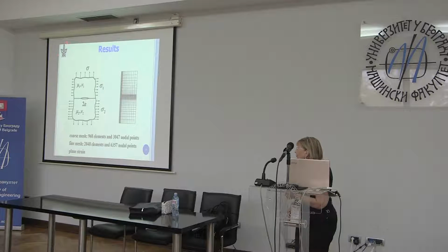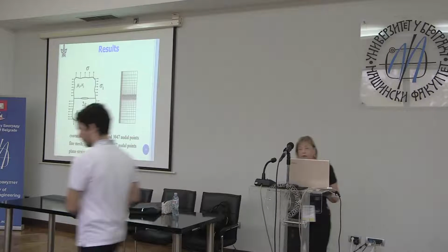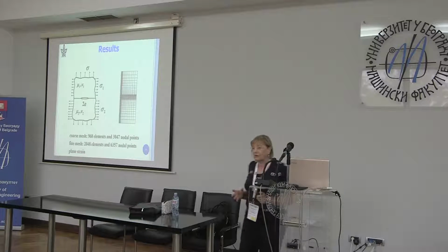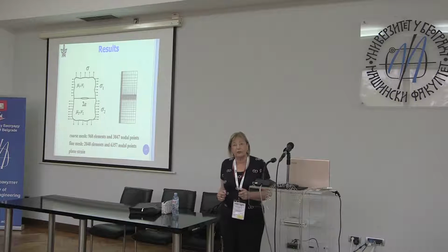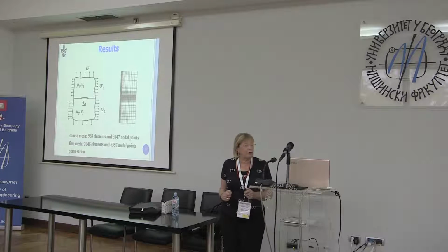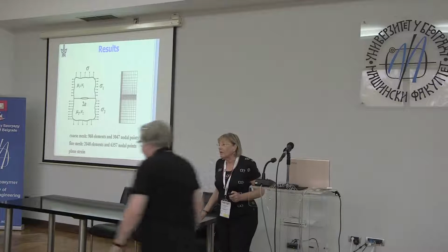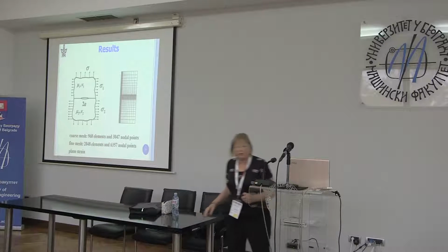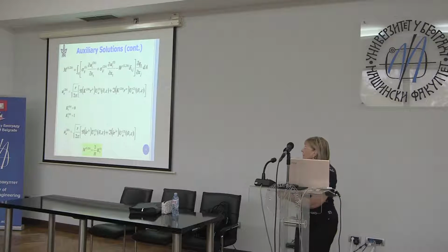Okay, so what I described to you before the break was a numerical technique, the conservative M integral or interaction energy integral, which can be used to calculate stress intensity factors with finite elements. We calculate the integral.